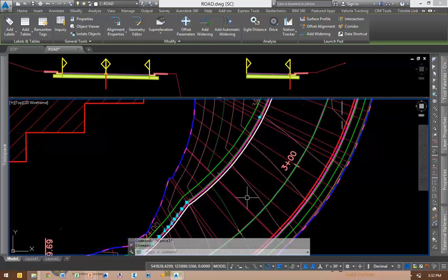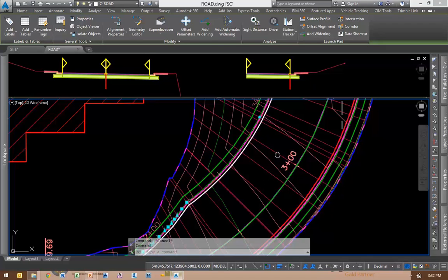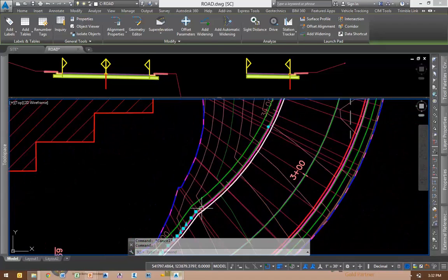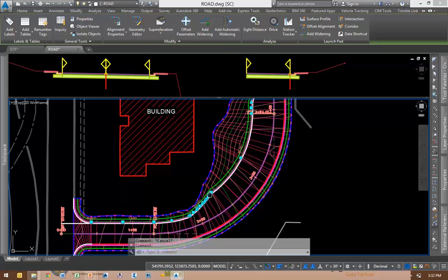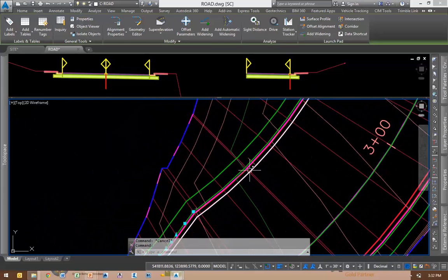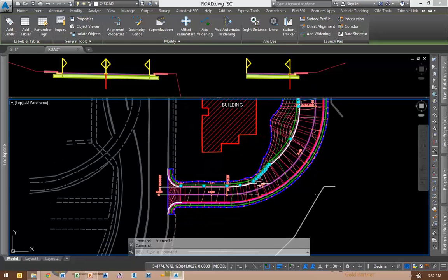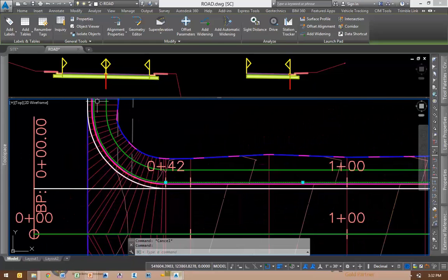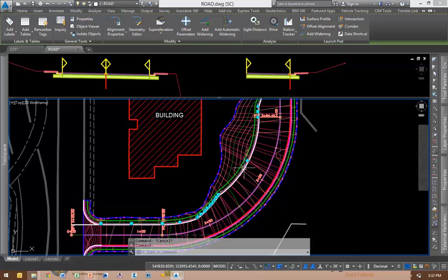Yeah. So those of you familiar with corridors, how many people use corridors on a regular basis? Okay. We understand what feature lines are in corridors. There's no curves in a corridor, is there? It's all chords along curves. Civil 3D is actually smart enough in this way that it gives you a curve along curves. It's kind of a nice feature there. The feature line, if we extracted that, we'd get a whole bunch of little chords. Again, though, that's stationing not based on center line. It's going to have its own random stationing, and it's only going to do it for a given region. The alignment doesn't go all the way around here. So if that's something that's going to work, that's a nice way to pull that stuff out of your corridor.